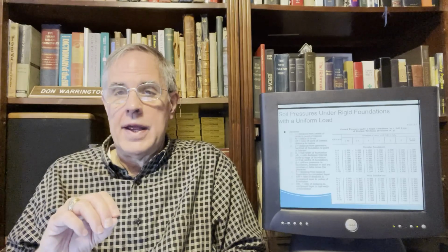But basically the bottom line is this. First of all, the numbers here are fractions of p. You remember maybe from soil mechanics we talked about influence coefficients. Influence coefficients were the ratio of the uniform pressure at the surface to a pressure in the soil mass. And that's pretty much what we're talking about here. We start with the centroid and we go out with little r, or we go out with little y, to a point where we hit big R, the radius of the circle, or B, which is the half width of the foundation.